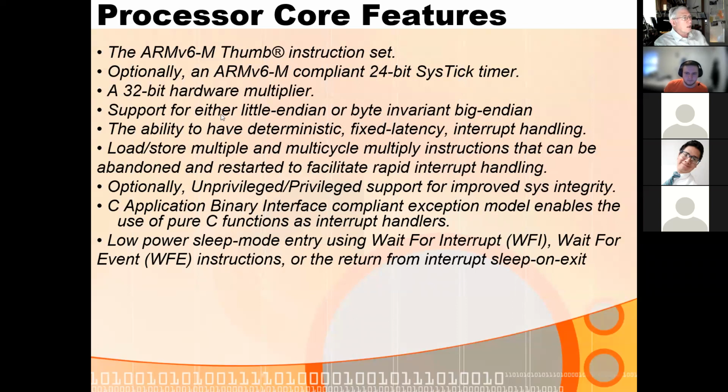When you incorporate the ARM core into your peripheral functionality in the Verilog file, you pick at that time whether you're going to address memory in little endian format or big endian format. And Freescale selected little endian, so it is set up as little endian.